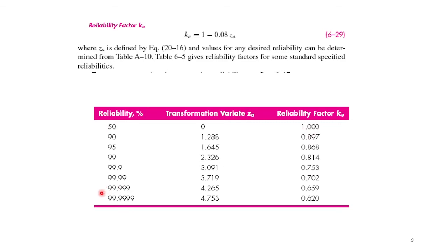And this is the value for a part or component that is in a crucial machine. So this is 0.62. See how much you take off the S'_E: here you're taking around 38% off the endurance limit that was calculated from the S-N curve achieved inside a lab.